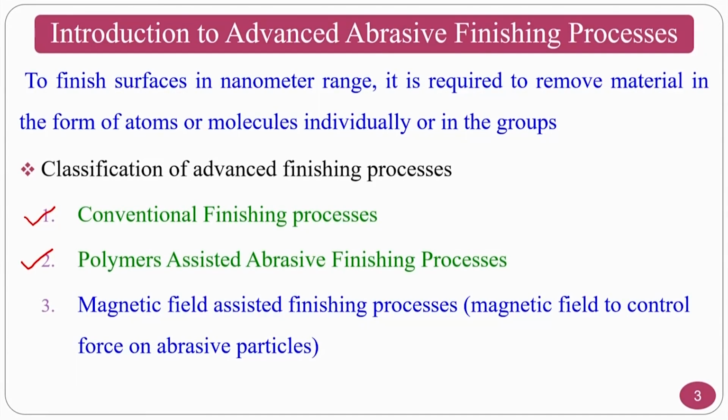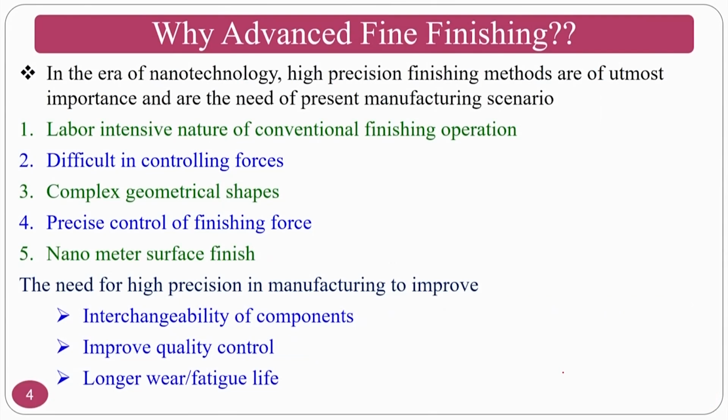That's why I have not touched much on the polymer assisted abrasive flow finishing processes. However, I am going to give you some introduction to the magnetic field assisted finishing processes, where a magnetic field is used to control the forces of this particular process.